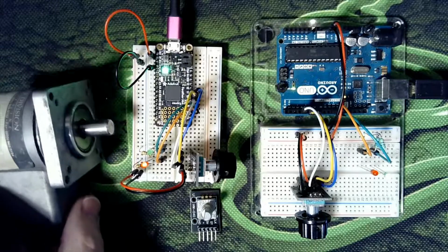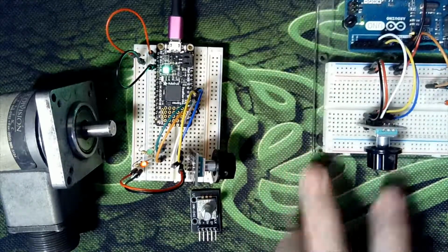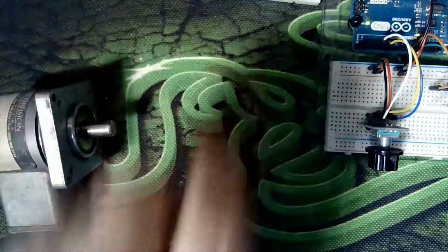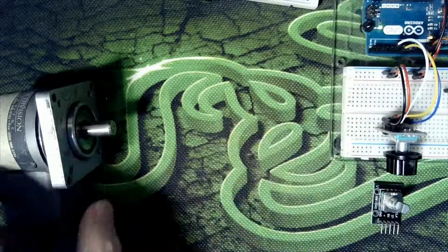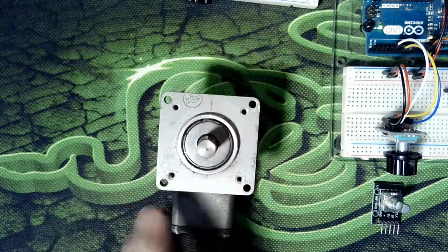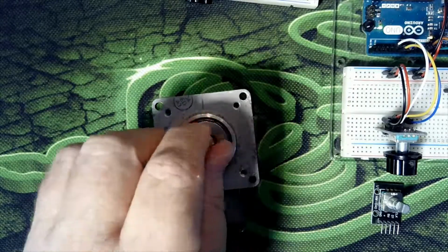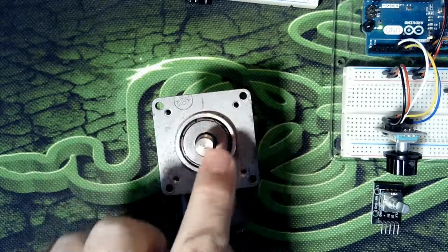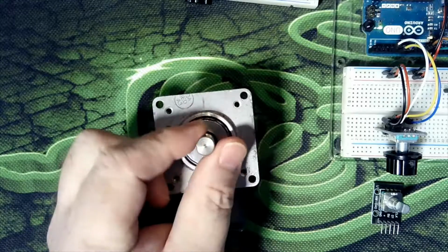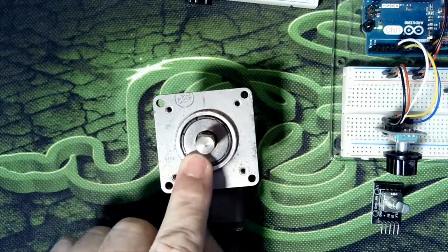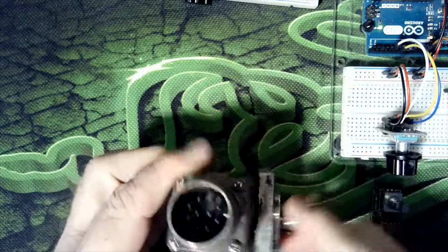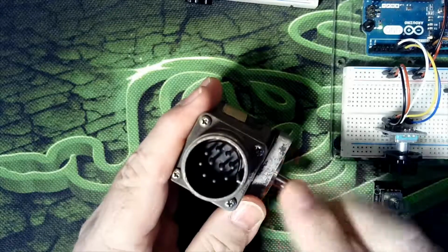The other thing I have here is this great big one. Let me just slide these two out of the way for the moment. Let me show you a little bit more about what a commercial one looks like. These are commercial encoders. This is a full-blown industrial encoder. This is a very sealed package. This has been used out in the field before. It's not perfectly clean. This one here counts 500 counts for every revolution of this shaft. And it is very smooth to the touch to move. It's very, very fine. It's got a high quality, permanently sealed bearing, so it's lubricated. It has a large connector, what they refer to as an Amphenol, not just the company that makes it, a multi-pin plug.